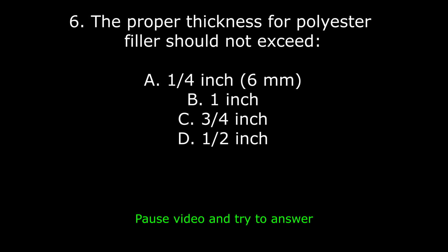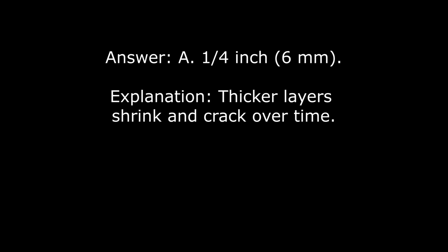6. The proper thickness for polyester filler should not exceed A. 1/4 inch, 6 millimeters. B. 1 inch. C. 3/4 inch. D. 1/2 inch. Answer A. 1/4 inch, 6 millimeters. Explanation: thicker layers shrink and crack over time.